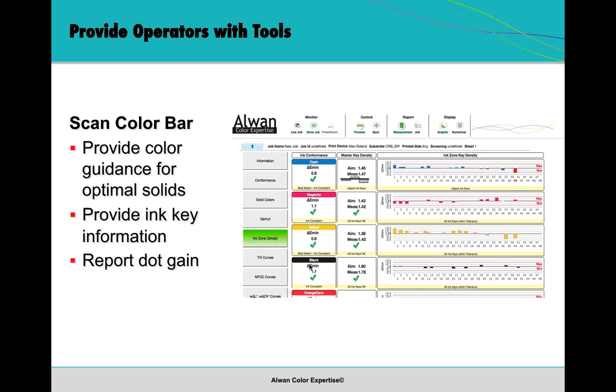Now, this is a key story. We were in this shop initially trying to do a hi-fi color press run for G7 plate curves and the tone value curves for the hi-fi colors. And they were using a handheld device doing point and click on the color bar off the top of the page. Are you kidding me? This is a 56-inch page doing a handheld point and click for 7 colors across 40 ink key zones. It took 4 hours to get anything that was even usable.